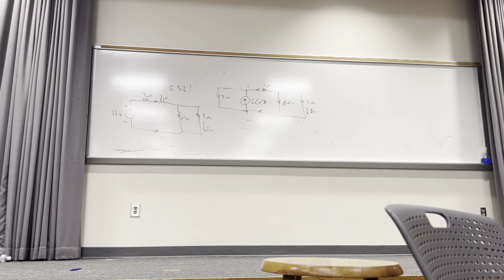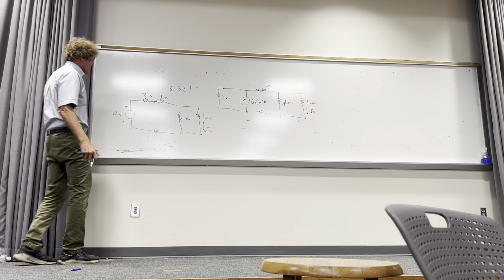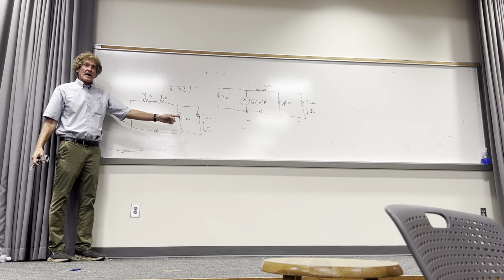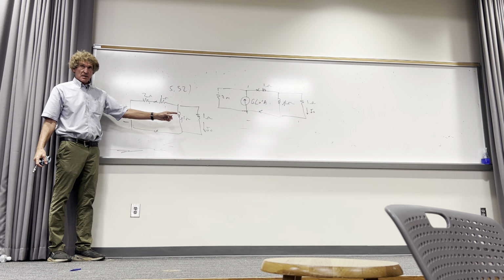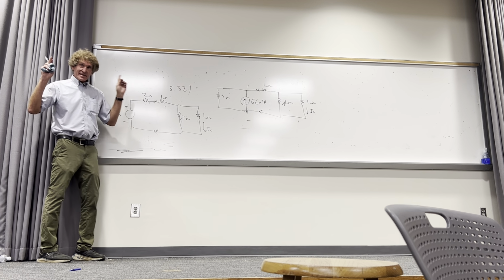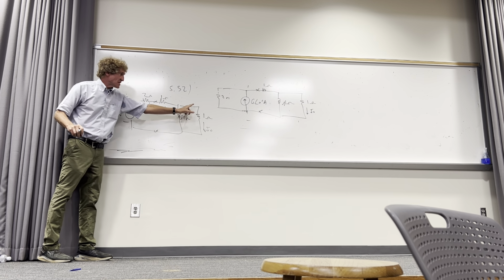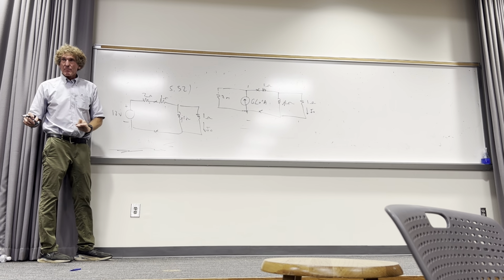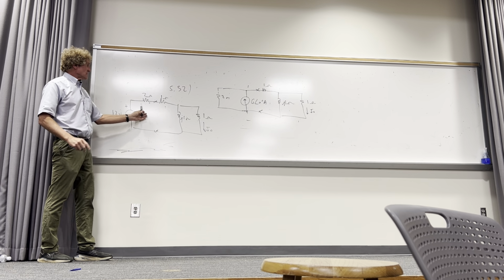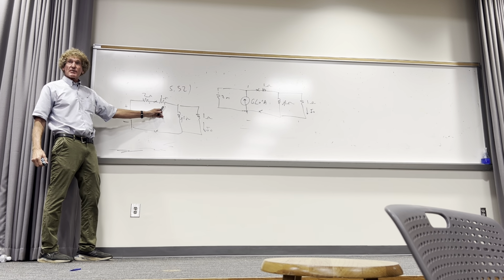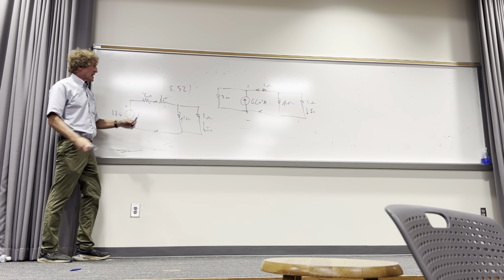Show of hands if you can see this. Now, this one is a little more attractive. If I want that current, how would you get it? Well, not quite, yes, you could do voltage division first, but then you'd have to divide it by 1 ohm. But before you got that, couldn't we simplify a little? You agree with that? Sure, make it 3 ohms.